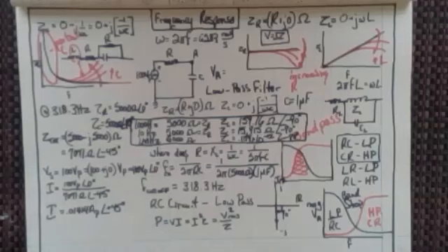And that's another way that you can always check. If you're working on an oscilloscope and you want to find out what your resonant frequency is, and you don't really know what the resistance and the capacitance are in that RC circuit, you could easily figure that out, because you just dial it in until you see that the current compared to the voltage is at a 45-degree phase shift.